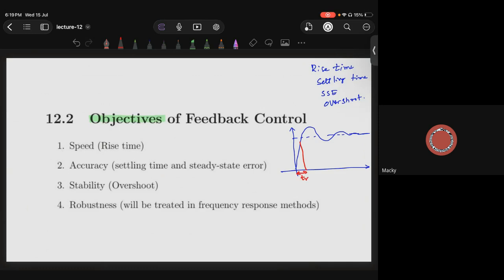So this is the TR, which goes from 10% to 90%. Okay. Then this will be what? This will be overshoot. Okay. Then this will be settling time. Then this will be SSE, that is nothing but the steady state error. Clear? So these terms are defined for both first order as well as second order systems.